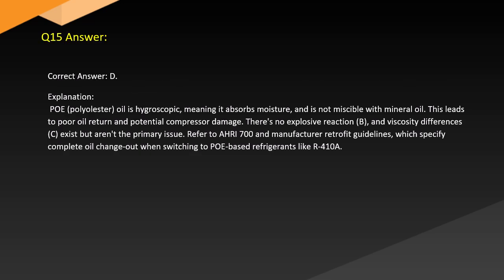Answer. Correct answer D. Explanation. Polyester oil is hygroscopic, meaning it absorbs moisture, and is not miscible with mineral oil. This leads to poor oil return and potential compressor damage.